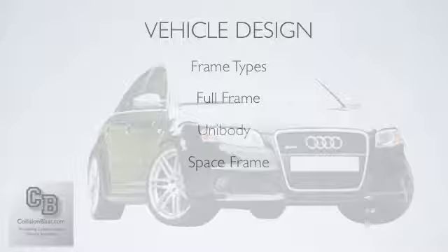Now, unibody, that's where all the structure is one piece. So you've got, like I said, all the frame rails, the floor pan, all that is welded into one piece, and they're usually welded together from the factory. Different methods. Probably the most common is spot welds, and that's where the machines go in and they squeeze the metal together, and there's no filler metal added. It just squeezes it together real tight, heats it up, and fuses the metal together. So you'll just see round dimples where this happened, and that's a spot weld.